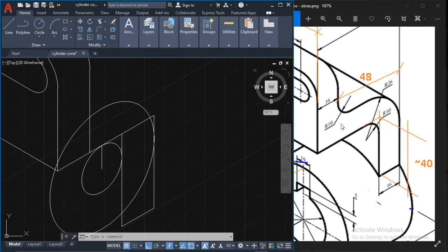So it says that this distance is going to be 16. And we know that this is going to be 16 because the line that we're going to draw across is going to touch the top of the circle, or one of the quadrants or tangential points. And if this distance from here up to here is 26, and from here to here is 10, that means that the rest of the distance is 16.